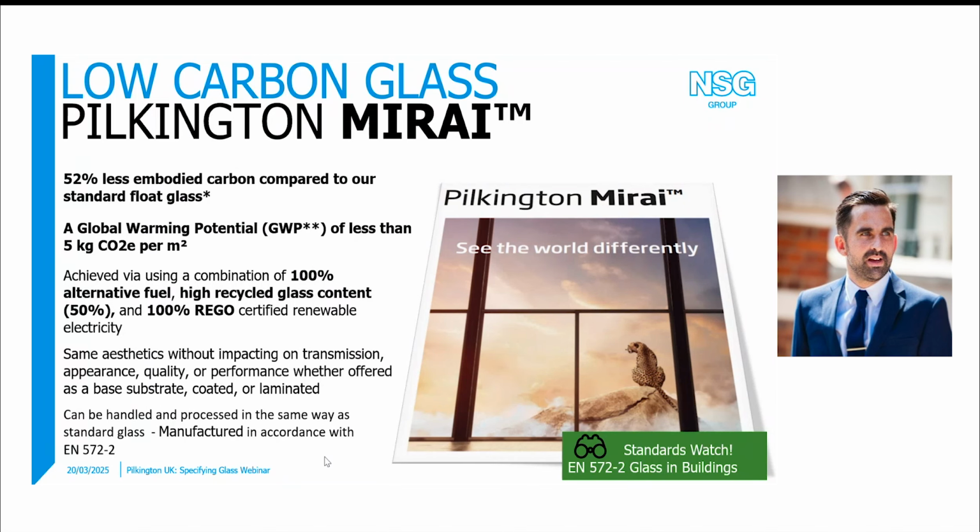High recycled glass content, so we'd have 50% cullet used in our batch mix. A typical batch mix for standard float glass probably has somewhere between 15 to 25% cullet use. So we always use cullet, but when we're running the Mirai campaign, we use more. And that's where we need more of the external glass. So the glass from our unit makers, that's pre-consumer, and also, of course, the post-consumer glass, the end-of-life glass from buildings.